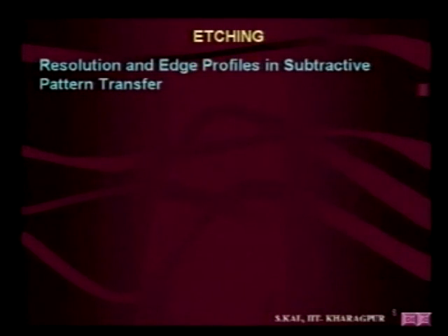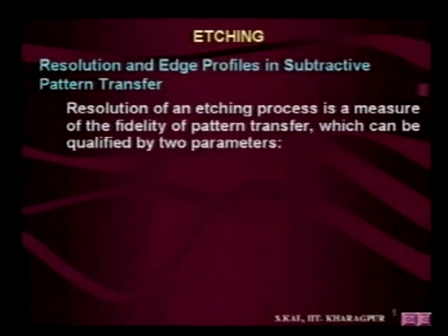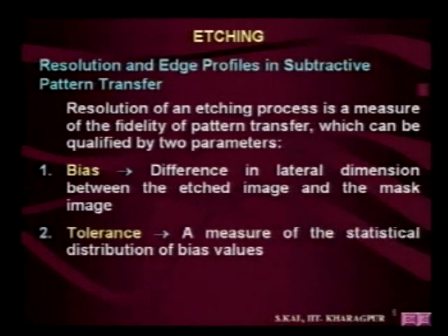Now, resolution and edge profiles in subtractive pattern transfer. Subtractive pattern transfer is the normal technique we usually use, and we will discuss some of its features. One of the features is the resolution. The resolution of an etching process is a measure of the fidelity of pattern transfer, which can be quantified by two parameters, namely bias and tolerance.